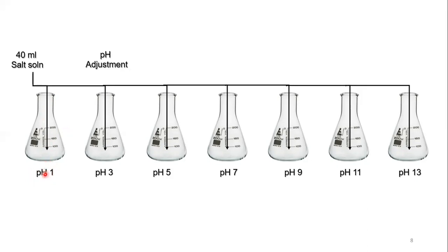Now when you reach a pH near 1, that is 1.3 or 1.4, then you have to use a dilute solution. Because if you still use a concentrated acid, it will change abruptly, and there will be a big change. So try your level best to handle it in such a manner that you can adjust the pH to your required level.